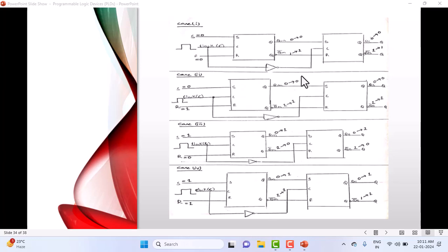And in this case 4, you can't eliminate this undefined state. The only way is you have to modify this circuit in some other way and come out avoiding this kind of undefined state. What is that circuit modification? It's nothing but the JK flip-flop. That's the modification suggested for SR flip-flop. Okay, any questions about this?